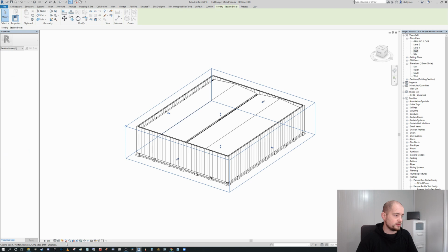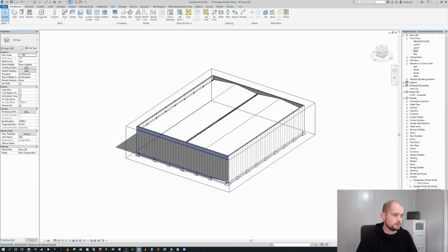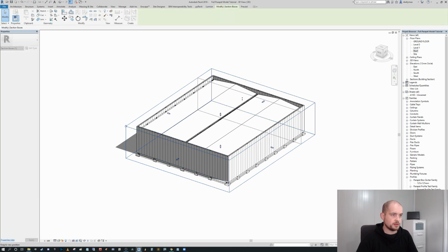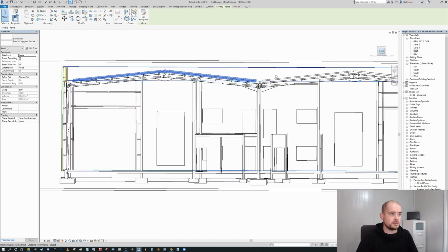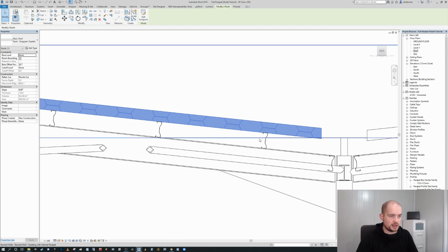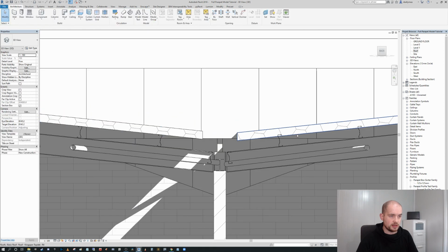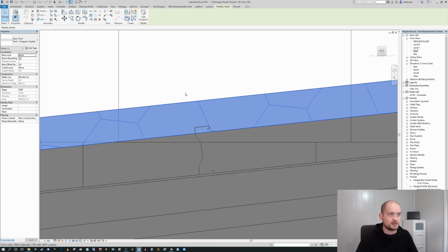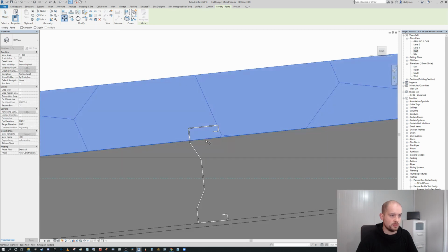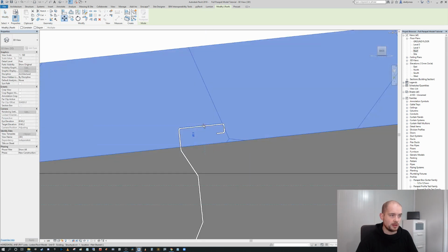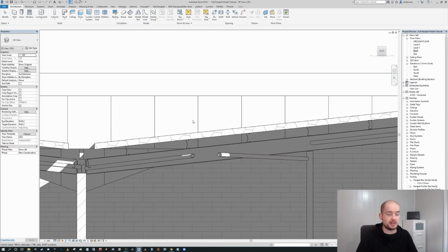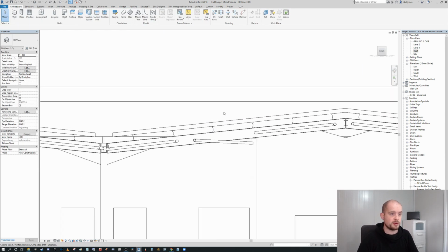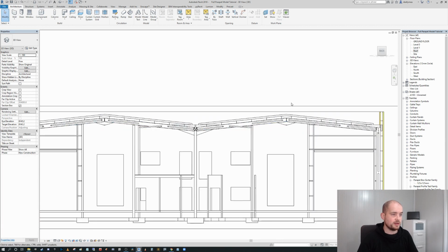And I'm going to, just for a bit of depth there, drag that down here. Looking in view here, you can see here's the roof we created, and our offset value is not correct. So I'm just going to use the move tool to the underside of the roof, and I'm going to say that's 27.1, perfect. Now you can see it's aligned perfectly to the top of the purlin run on either side of the roof.